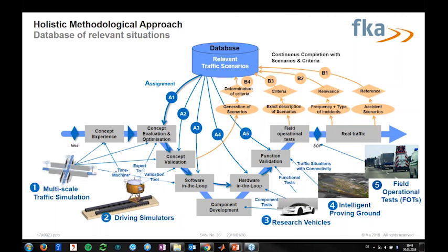So I've seen there's the first question about the 50 meters. There is no research done on why it is exactly 50 meters. This is just a rule-of-thumb value. From the experience I've had in the tests, I've driven, I would say, over 10,000 kilometers in a platoon. If you have a 10-meter gap, you won't see anything around in front of the first truck, for example. If you have a 50-meter gap, you feel much safer as a driver in the following truck. Also, it's a kind of distance we experience a lot on highways today, but there's not really a study that says, okay, 50 meters is the gap we should use. It's just a rule-of-thumb estimation.